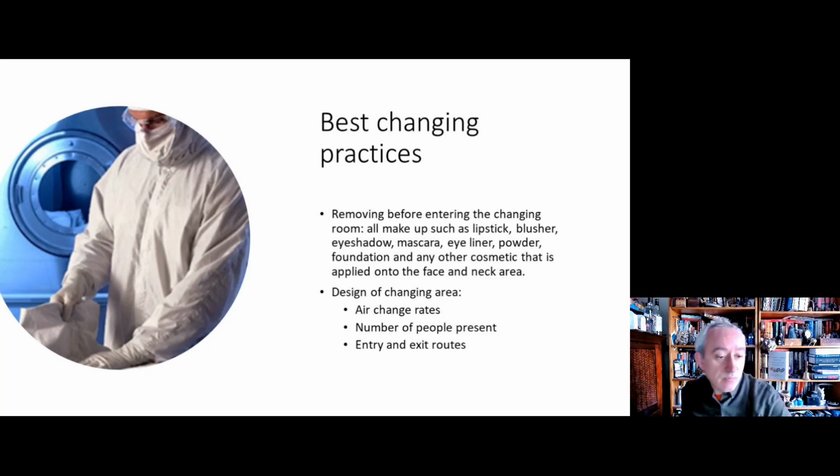So what are some good practices for going into clean rooms? Well, as I said before, ideally don't come to work with makeup on. If you do come to work with makeup on, then remove it and make sure there's no traces at all, and then make sure that you're doing the hand washing and all the other aspects. And then our changing areas are also well designed. So we do have slightly higher air change rates in the clean room, so we're pumping in more clean air because we're recognising there's going to be much more particle shedding and particle deposition.